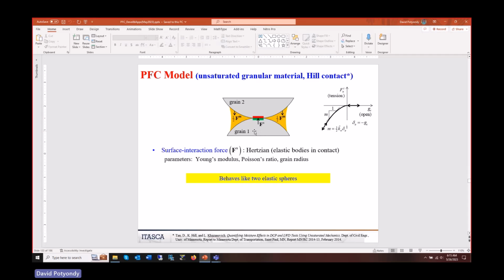And what I'm also showing here is the idea that we have liquid suction. We have an unsaturated granular material with a small amount of moisture. That moisture sits, because of surface tension, between the grains and causes a suction. And so I'm trying to show this yellow. It's supposed to be my moisture. Think of it as honey, think of it as water.